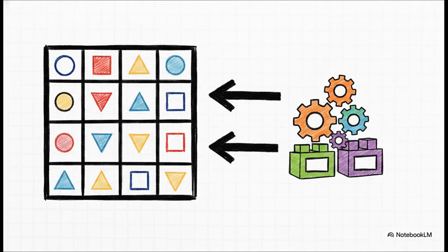So, how do we actually build the AR model in practice? We rely on the Yule-Walker equations. When we arrange the autocorrelation values of our desired signal, they form a highly structured matrix known as a Toeplitz matrix. The really brilliant property of a Toeplitz matrix is that it's completely symmetric, and all the elements along its diagonals are absolutely identical. This incredibly unique diagonal structure makes solving the matrix for our filter parameters incredibly computationally efficient.